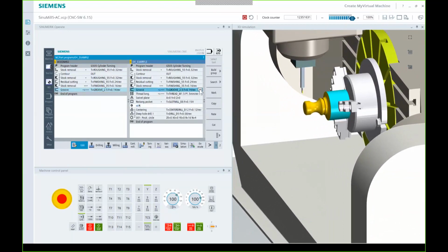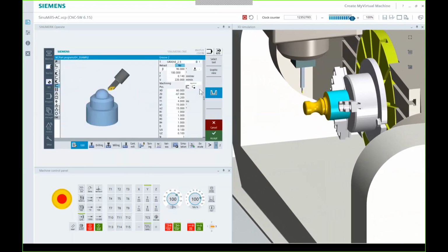So on the grooving cycle, just like the other cycles you've seen, and I know I'm beating this over the head, but having this beta and the gamma, and knowing how they work, is very, very important. In this case, I'm actually rotating the tool 180 degrees to engage the tool with the spindle direction on purpose, to a specific direction, because I want it to be moved in a specific direction. And my beta is rotated to me, obviously, because we want that bottom.